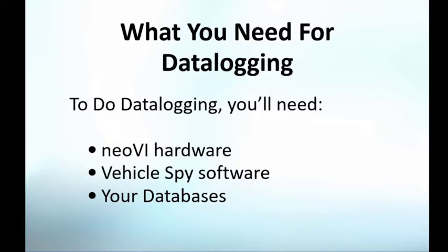Or let's say you wanted to log just a subset of messages. Maybe you don't want to log the entire vehicle worth of messages. You want to log 15 messages from one network and 5 from another. If you have the DBC files, again, all you need to do is select those messages that you want to log. When it comes to doing diagnostic logging or doing CCP, XCP, then it's pretty much a requirement that you have to have the associated A2L file or ODX file, whatever it might be.